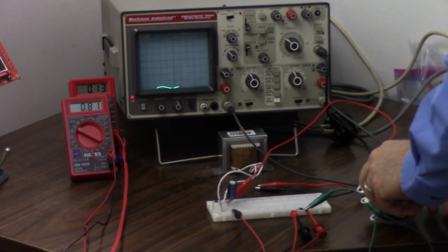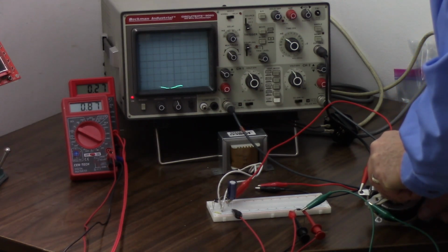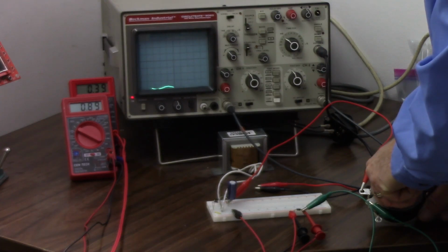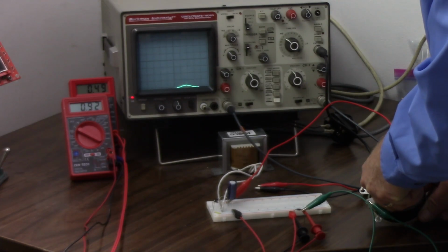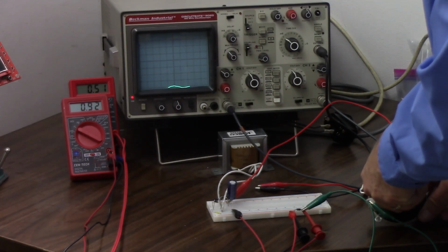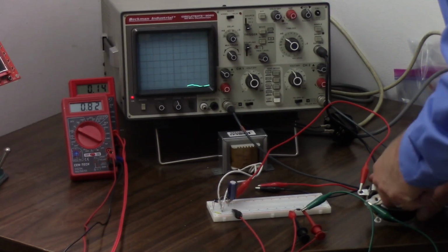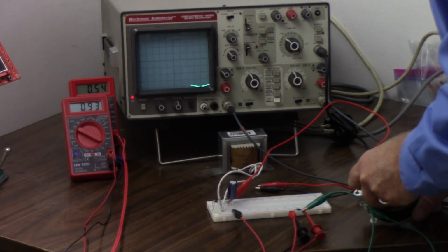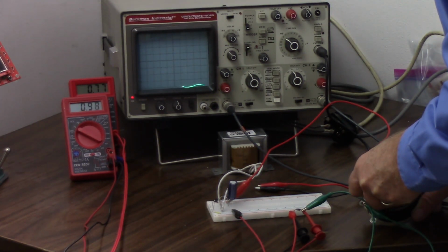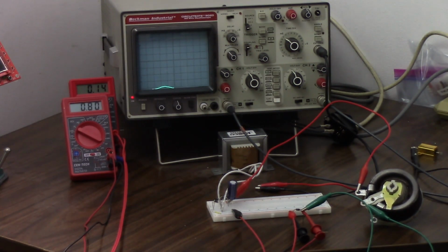Let's crank this up to a few hundred, to maybe 500 milliamps and see what that does. 200, 400, there we go. Oops, don't want to take it too high. About 500 milliamps, and we've got 0.9 volts across it. So we're getting a whole volt at only 500 milliamps. Those are 1 amp diodes. Let's see what happens if we crank it up. Let's see if we can get a whole amp through those. 0.9, half an amp, 6/10, 7/10. We're getting over a volt across that diode. What the heck is going on there?